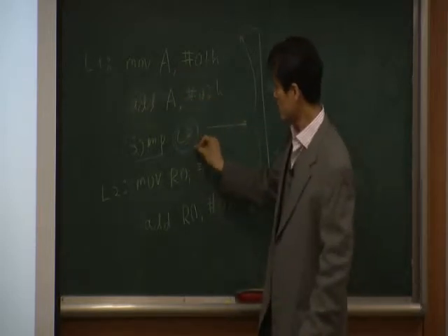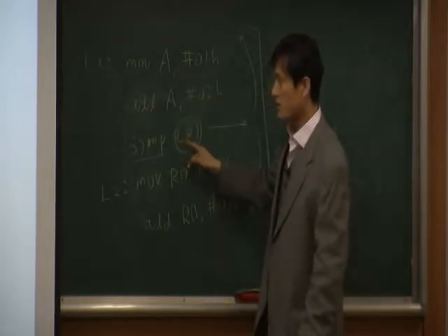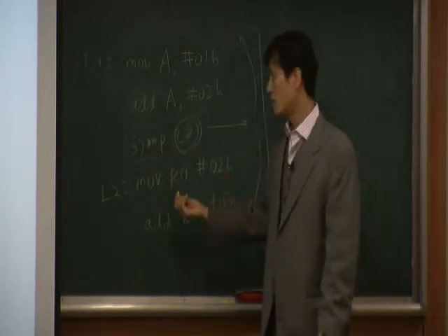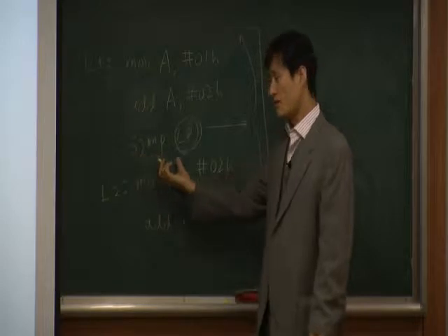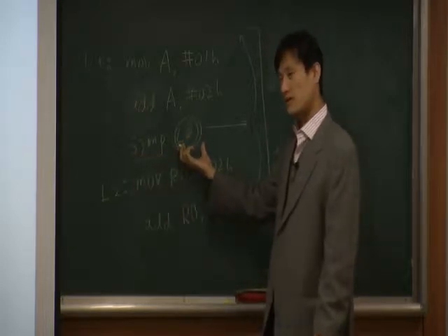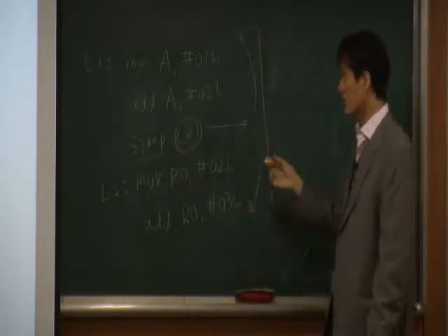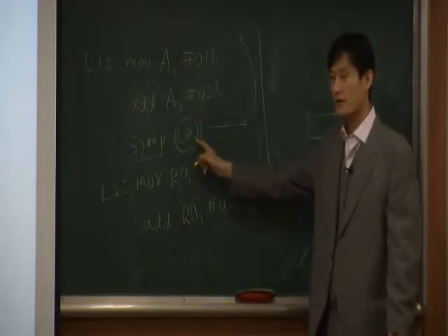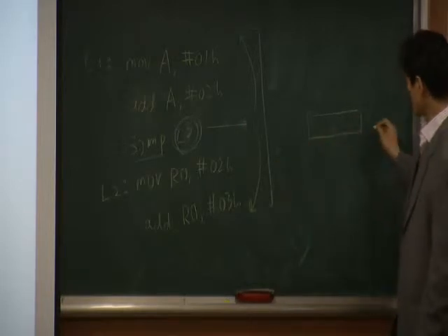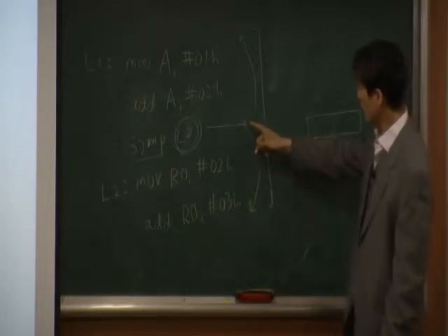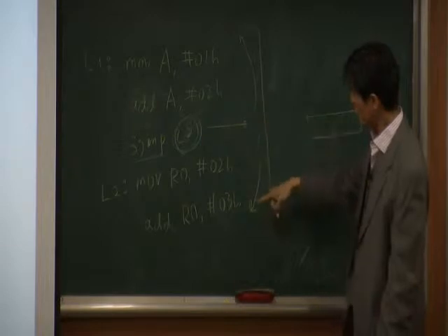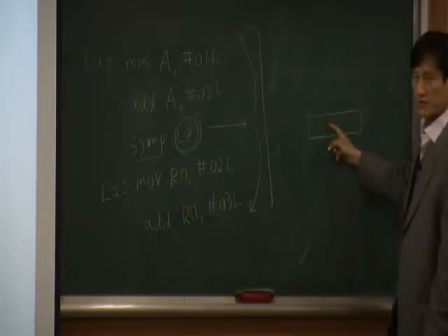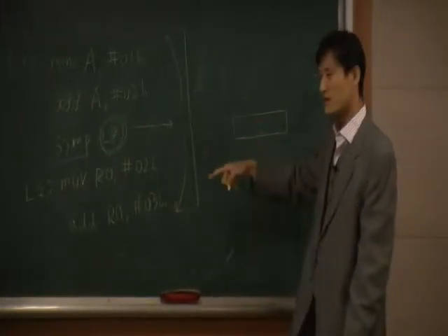Okay? But think about this one. This operand is going to be 8 bits. The opcode is 8-bit, and you have one operand in this case, which is another 8-bit. Since you have only 8 bits for this operand, and sometimes you need to go back or jump forward, we have to use a signed value. Sometimes we can have minus or sometimes plus.